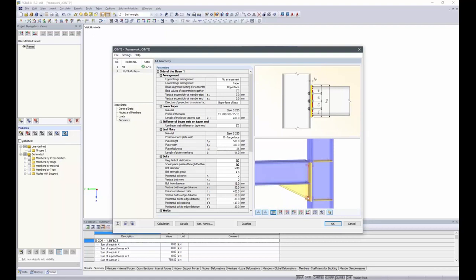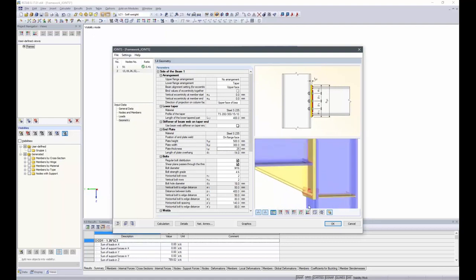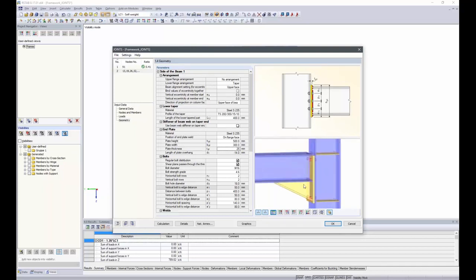The bolts are not in the right place yet, because this one collides with the flange of the taper, and that's not okay. And we want to have some more bolts anyway, so I changed that a little. I don't want to have a regular bolt distribution, so the height of the middle ones can change.